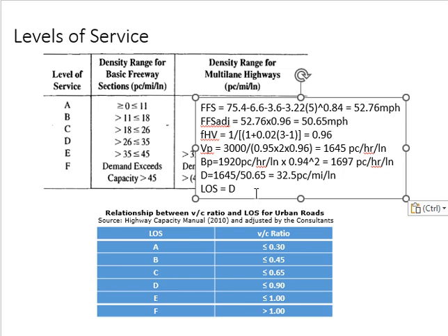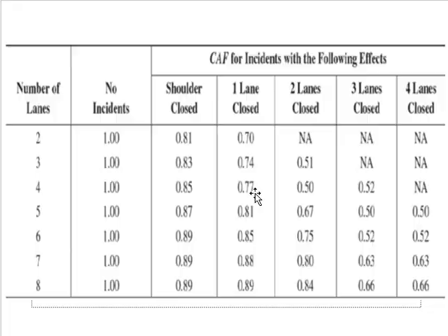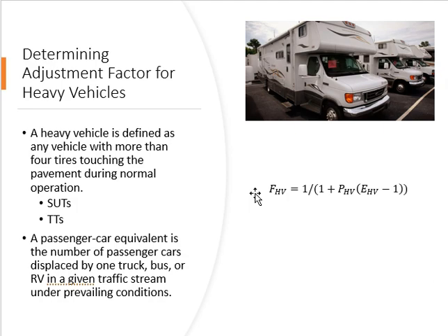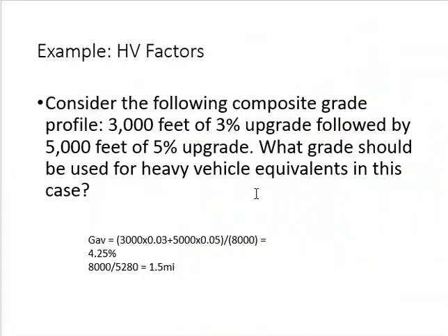What are the things which changed? Density changed. Density increases, that means traffic is becoming slower. Drivers are slower, their spacing is less, their speed is lower. And you can see the free flow speed is lower, obviously. So this proves that. You may not see any significant change, but there is a slight change in the speed and the spacing.